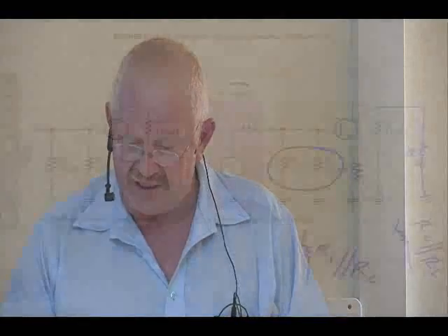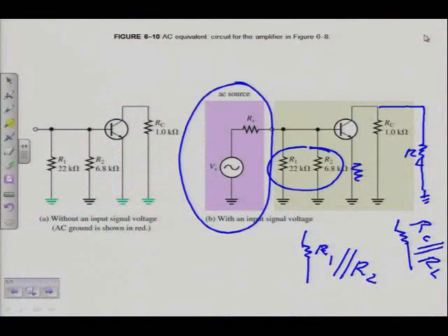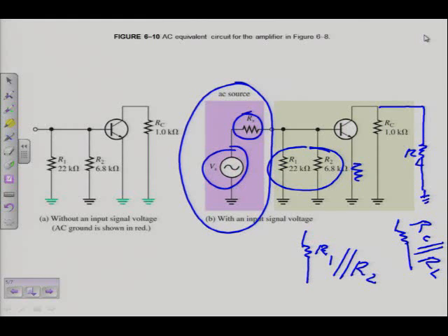Understand what you need to do. Work from the circuit that you were given so that you can see what is included and what not. All right, keep that in mind. Important here, as you can see, the AC source is in one colored block. The AC source includes the signal and RS, because it's one thing. RS is the internal source resistance.